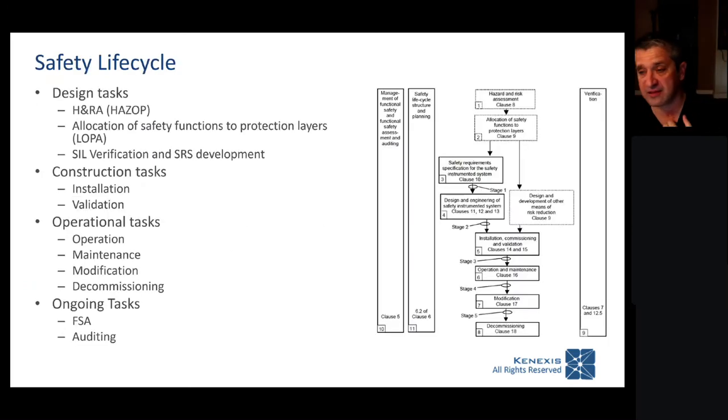Now, the slide that you see here, I'm sure, is extremely familiar. It is the safety life cycle in accordance with IEC 61511, and it talks about a variety of tasks that are going to occur over the life cycle. So you have your risk assessment tasks that are assigning performance targets to the safety instrumented systems.